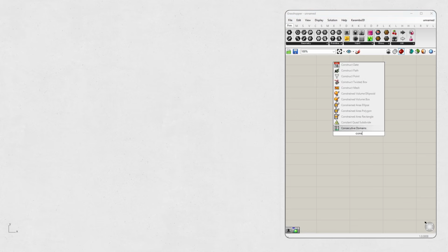All right, so here we go. It's time to create our very first data. To kick things off, I'm going to double click on the empty Grasshopper canvas to pull up the command search section. Now I'm going to type in construct point and select it from the list. This component is super neat because it lets us create a 3D point, and we can control the X, Y, and Z coordinates separately.